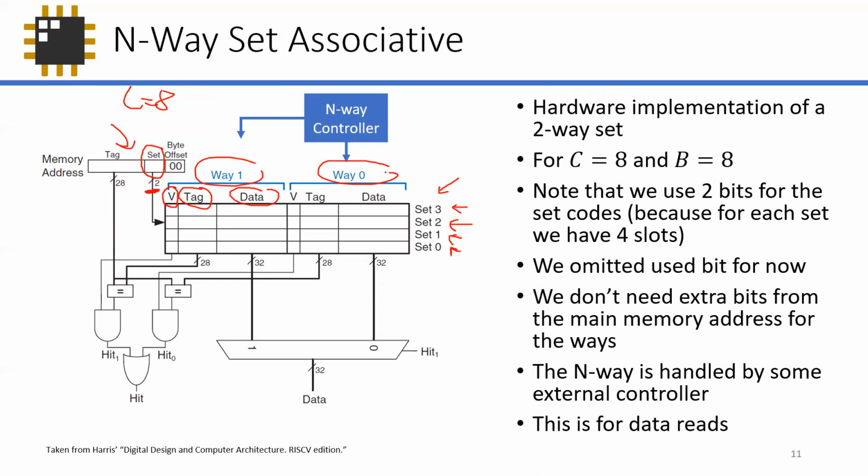So we're gonna decode it that way. It's not really a multiplexer, but really a decoder to indicate that this is the row that you're going to grab. Okay. And then after grabbing that, as I mentioned earlier, you have the only way to identify if you hit any of the data or any of the memory addresses in that set. Oops, sorry.